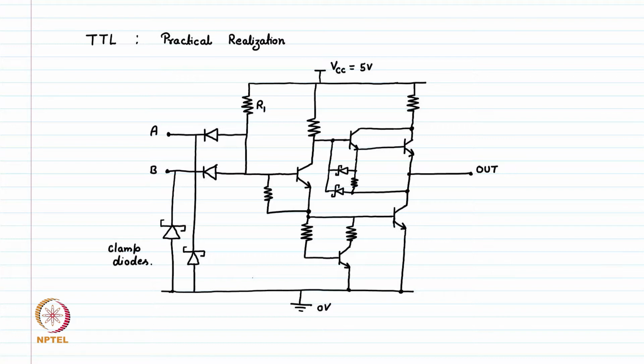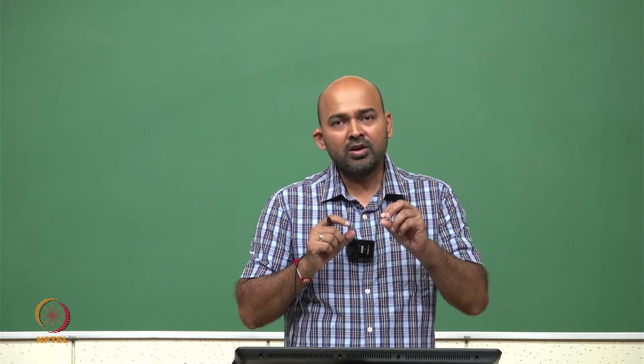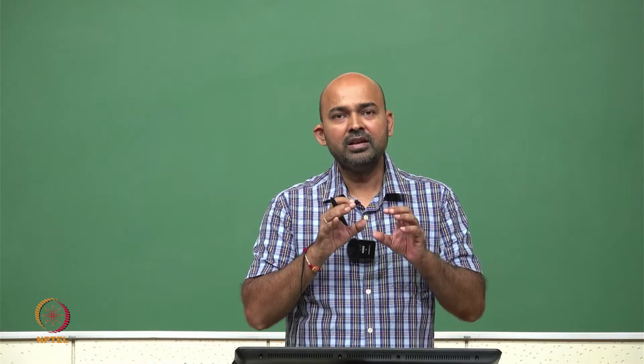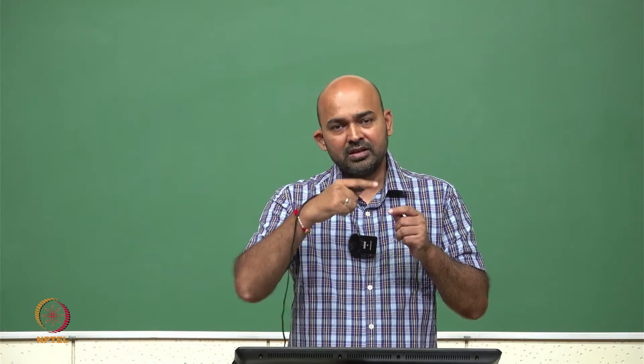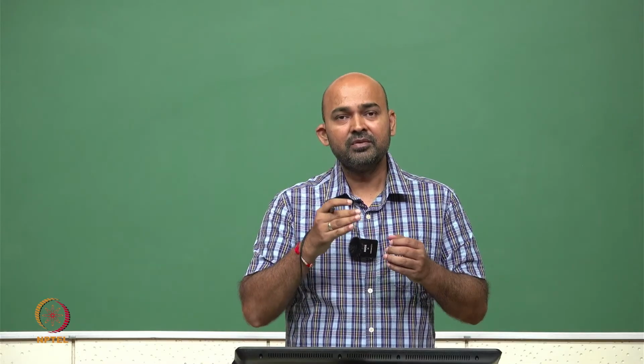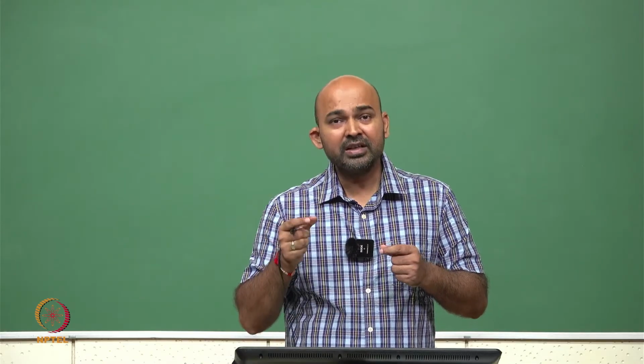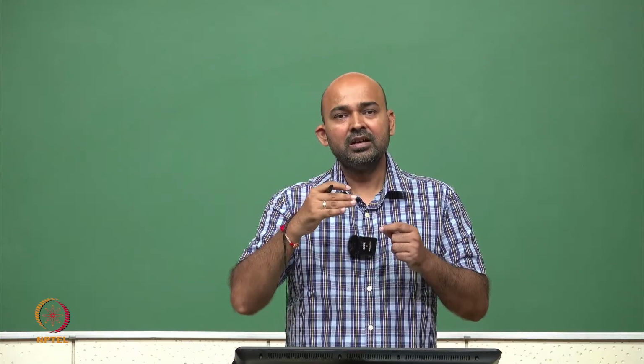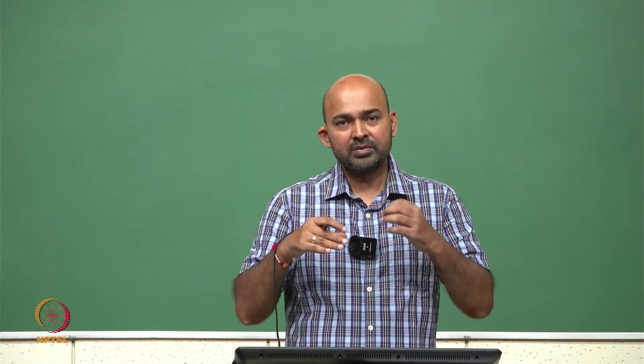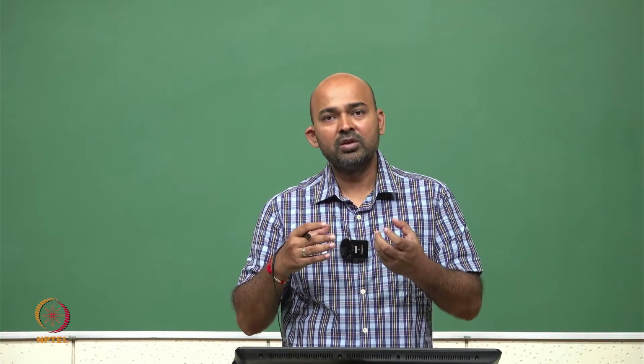when there is a device which is on, it is carrying a certain amount of current. As soon as we turn off this device, the wirings or the devices themselves have a certain amount of parasitic inductance. This current tends to flow despite our turning off the device.